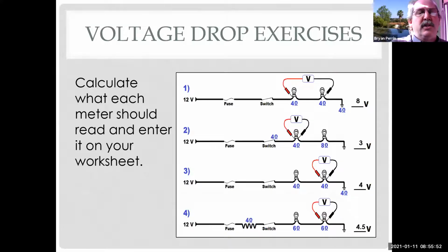So that's why test lights really fell out of favor, as well as you were really relying on how good a ground connection you were able to make. But I still own several test lights, and I fixed a lot of cars with them. But what we found is that I can have something light up with a test light and still not necessarily operate a load, or especially with computers, I'm losing enough voltage where the reading the computer's getting is not accurate. And that's why we don't use test lights on those circuits.